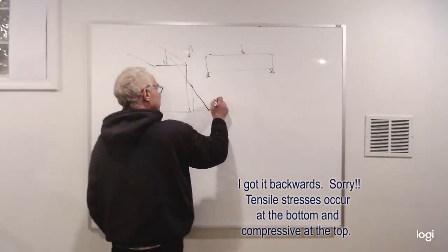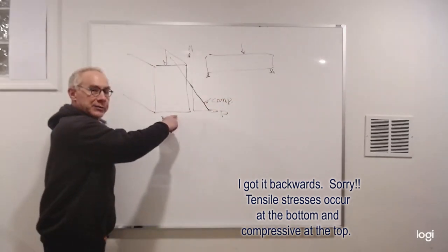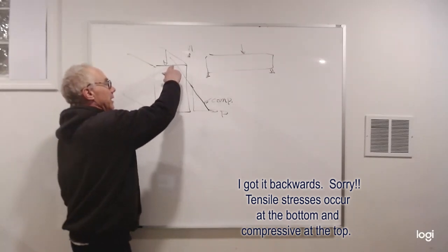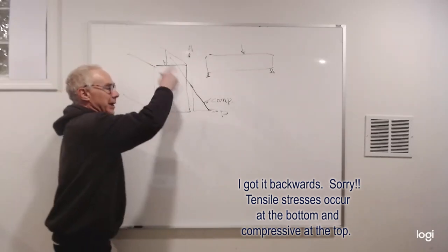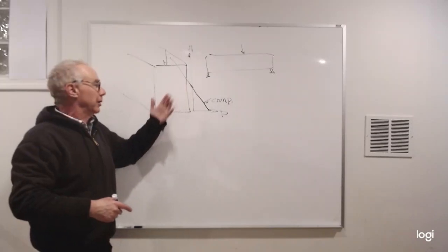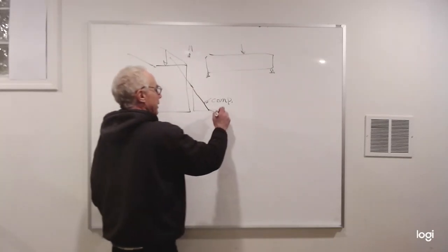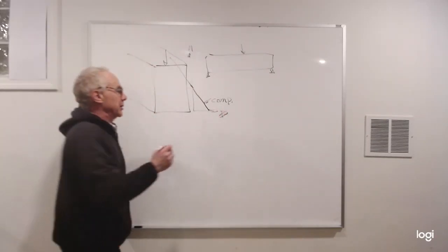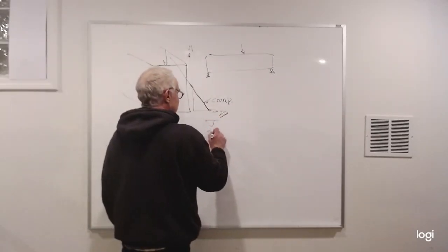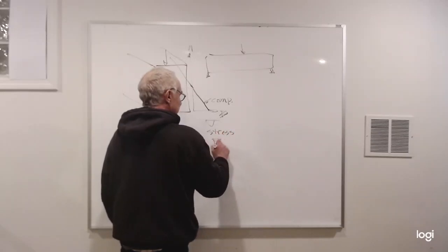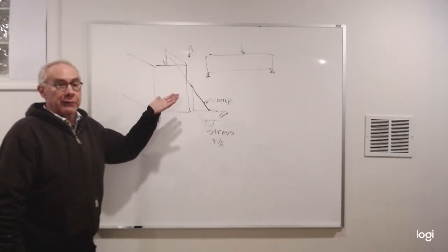So here we have stresses getting larger, and basically the maximum compressive stress is at the top of the beam, and the maximum tensile stress is at the bottom. And at the centroid, providing that the area is a homogeneous material, that's where we're going to have essentially zero stress. You could put a P for pressure, but typically we think of it as sigma for the stress, where it's essentially a force per unit area. Okay, so that's why we need to think about where centroids are occurring.